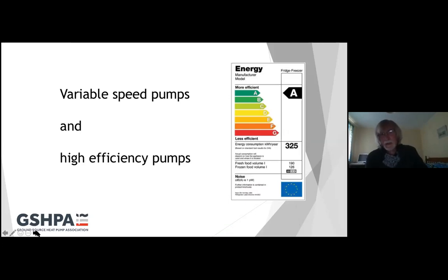Last area is that we're blessed these days with the big improvement in the technology in pumps. Just make the distinction that when the variable speed pumps came into vogue, they also came with new high efficiency motors, basically. And we're interested in both of them. Where you're after the variable speed, then yes, pick the new high energy variable speed pumps. Make use of the high efficiency technology.